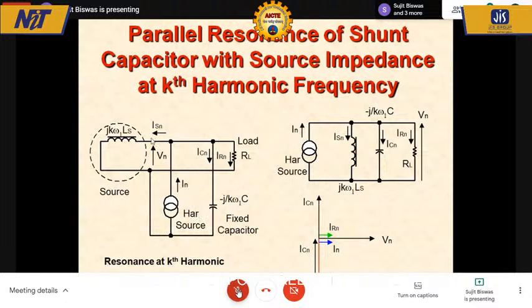You will not be able to explain that. And this current will be coming in through your distribution transformer level, which is stepping down 11 kV perhaps into 400 volts, your transformer losses will go up significantly simply because you have connected a power factor capacitor at your premises. This is the crux of the problem. You just can't do that. You cannot connect an arbitrary power factor correction capacitor in your premises. You cannot connect an arbitrary filter in your premises without checking for resonance with the system. How do you know what is the source reactance?